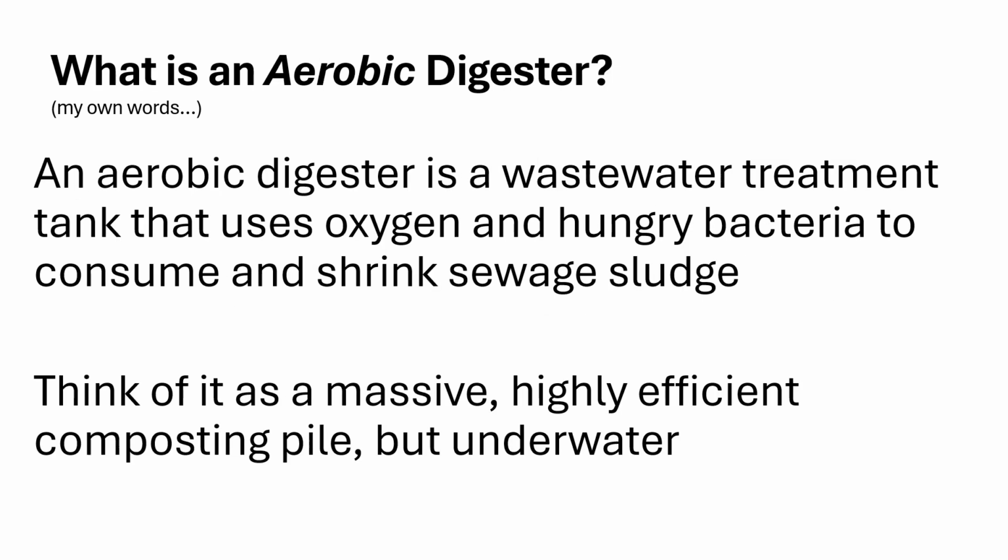and so we talked about anaerobic digesters. Remember, anaerobic digesters function with no oxygen. Aerobic digesters, it's wastewater treatment that's going to use oxygen. We want oxygen present, and it's going to say we've got oxygen, we've got hungry bacteria, and it's going to chomp away at those organics in that sludge coming in, and it's going to, what I call, shrink the sludge, the sewage sludge, by separating that bound water. It's going to separate the bound water from that sewage or that sludge, and it's going to increase the solids content. So that's an aerobic digester.